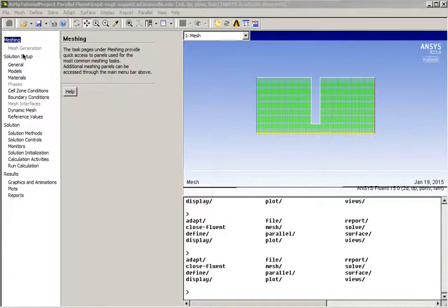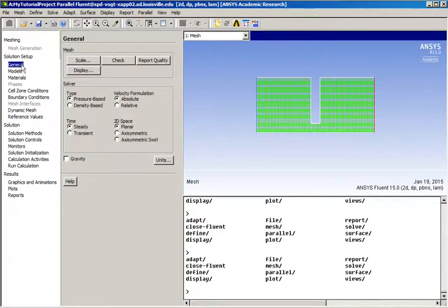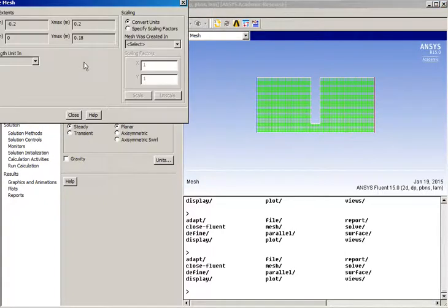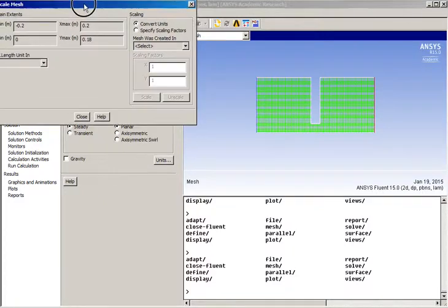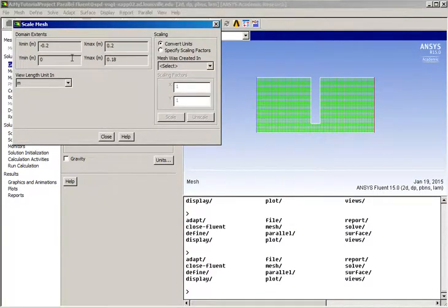We have to work our way down through the things on the side panel here. Just like usual, they make you work through these step by step. In scale, that's the most important one for us, and the weirdest thing we have going that a lot of these examples don't is that we're at the micro scale. And being that units were in meters, in my input file, I have something that's 0.2 meters in the minus x, and 0.2 meters in plus x, 0.4 meters across.